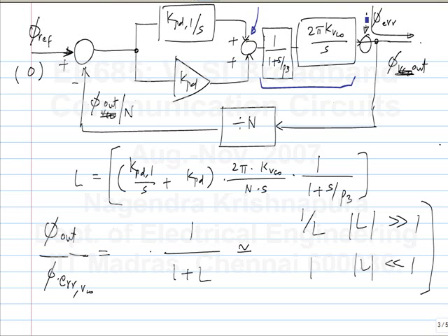So we know what happens if you add an error here. Can you figure out what happens if you add an error here? It's just divided by the scaling factor, right? So adding this multiplied by this whole thing gets added here. That's the net effect. So I know the transfer function between this and this, I divide it by this transfer function. So what does that look like? Band pass.